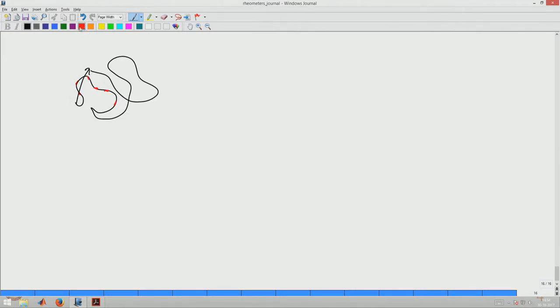So, it is like saying that I have lots and lots of small vectors. If I add all of these vectors, then I will get my eventual end to end distance, and this end to end distance is based on addition of all these dipoles. So, by knowing how the dipoles are orienting in general, I can also have an idea about how the overall molecule itself is orienting. So, in fact, you can distinguish between reptation motion, which is the whole molecule itself moving, using dielectric spectroscopy. You will not be able to do that in what we did in all of our rheology.